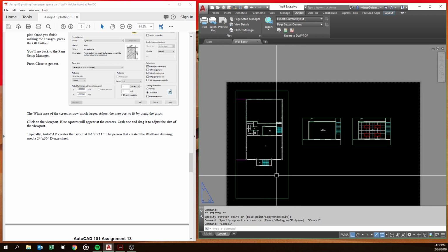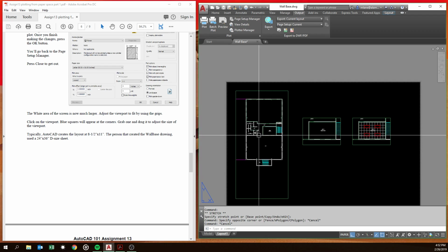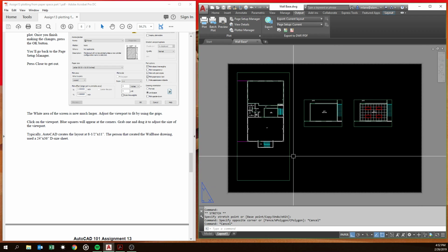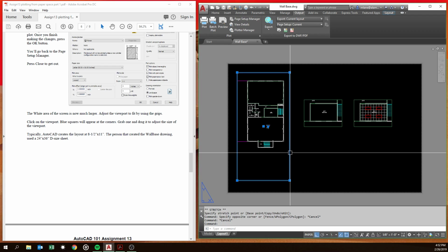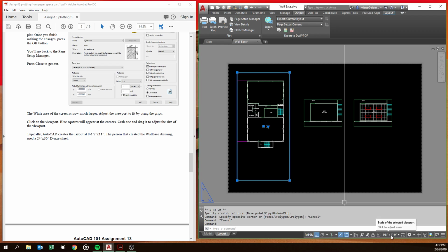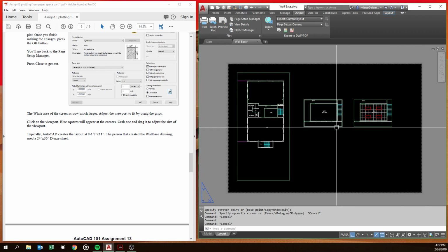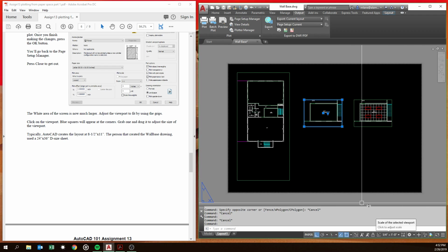So we could have one that's here, and then it has like a bubble here that shows you to zoom in and all this other stuff. And that's how we can create a drawing with multiple viewports. The viewport's just like a big camera way above your building or your floor plan in space, and that camera's just zooming in and out. In this case, it zoomed in to where it's 1/8 of an inch. In this case, it zoomed in to where it's 1/4 of an inch.